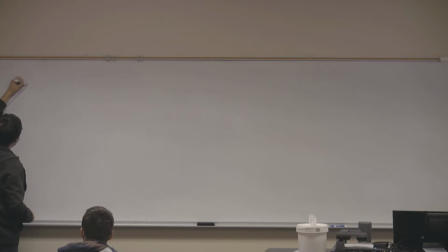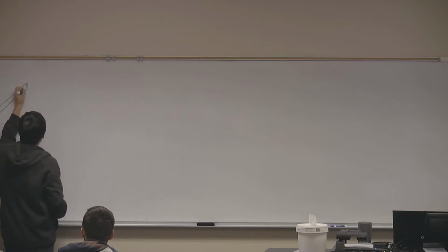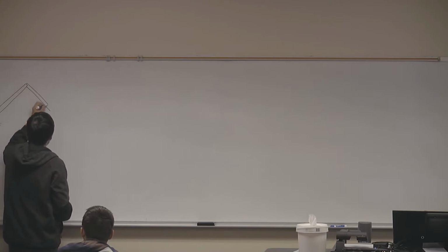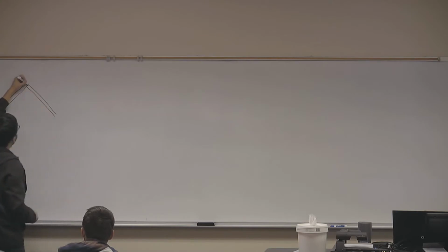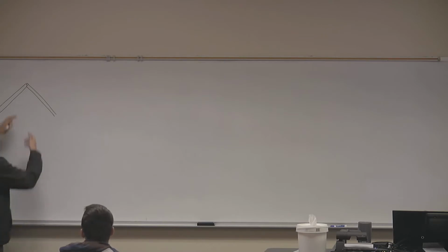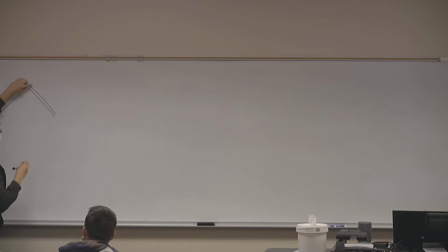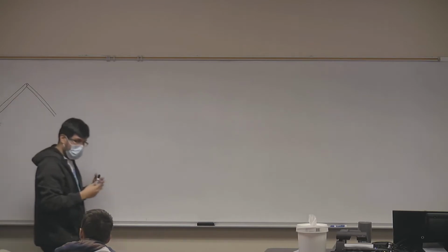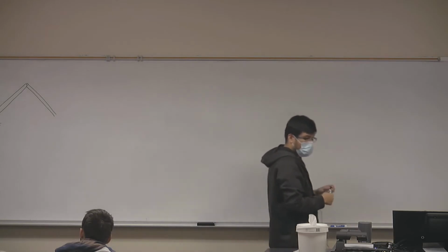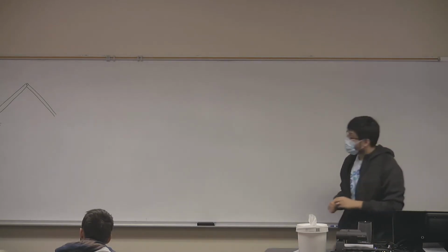And now let's say that this truss is connected to another truss. Now what does this tell me? Well, the connections between trusses will be treated as if they were hinges. In other words, those connections will prevent any relative movement in any linear direction, but don't necessarily have to prevent rotation between them. So when we look at two trusses connected, you can assume that that connection will be a hinge.